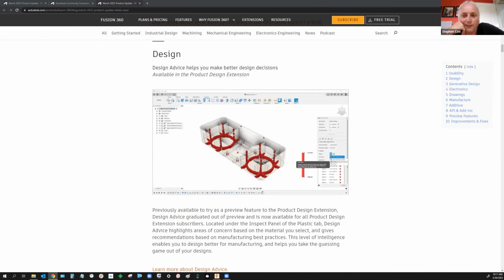I get frustrated by having to look through the browser and then hide the visibility of the objects that I don't want to join. Yeah, it's one of those things I think is too in the moment for something like a selection set, right? One of the ways to manage several components and turn them on and off with visibility very quickly is you could create a selection set, and you would select the selection set and hit the letter V, and the visibility toggle kicks in and turns them off.